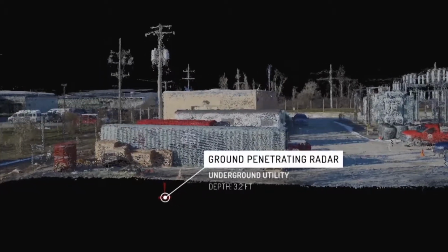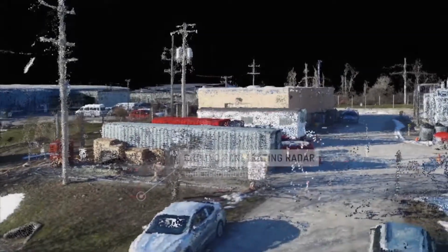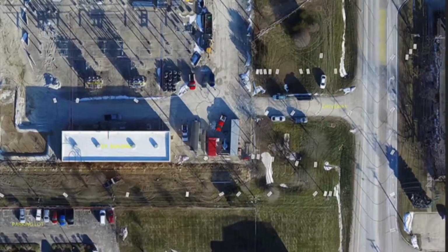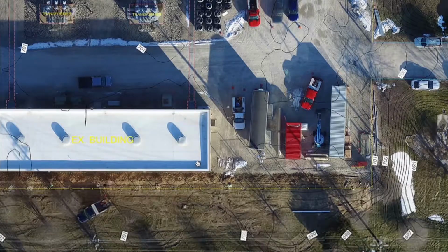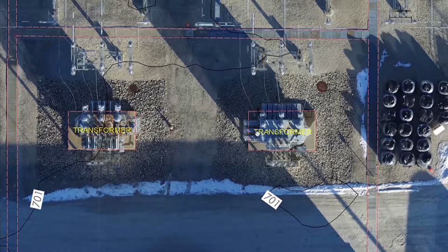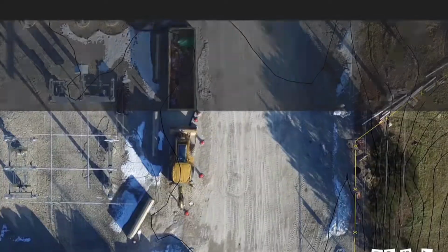The model is then mapped to geospace through a handful of traditionally surveyed ground control points. This then enables the production of topographic surfaces in context of high-fidelity aerial photography as a ground truth baseline of existing conditions for design.